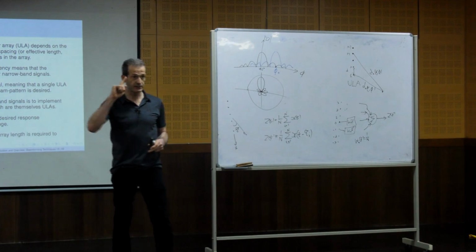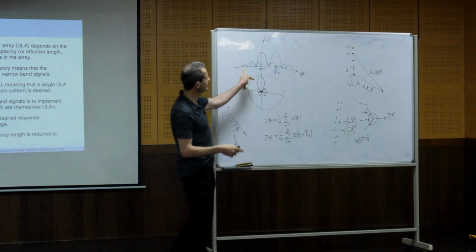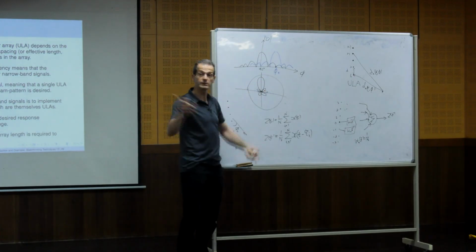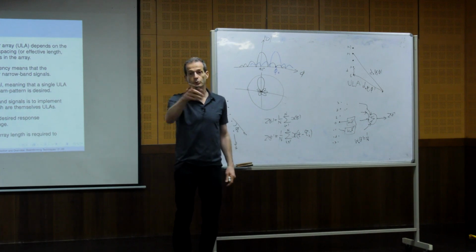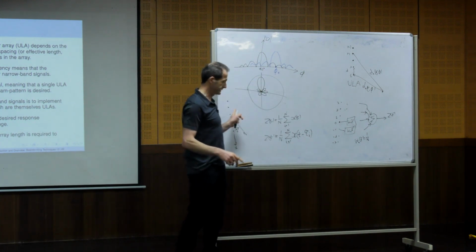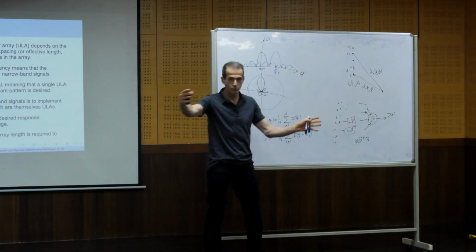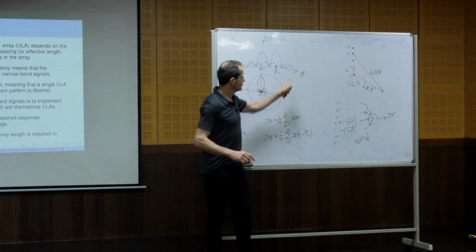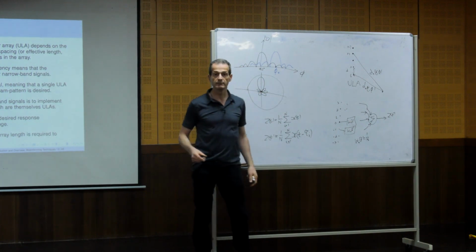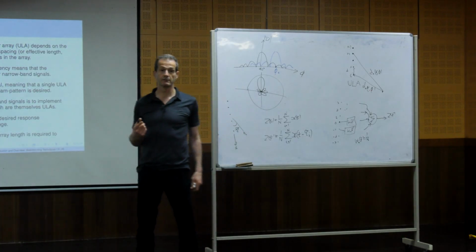Also for adaptive beamforming, even if I do steering to a certain direction, because I know that the source comes from a certain direction, I can do digital steering. Digital steering means that it's done according to the weights. I don't need to move the array to the side. But maybe this direction that I estimated is inaccurate.